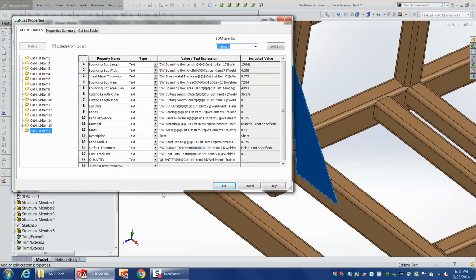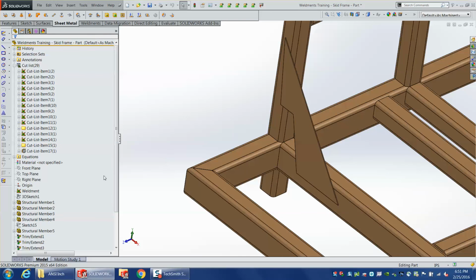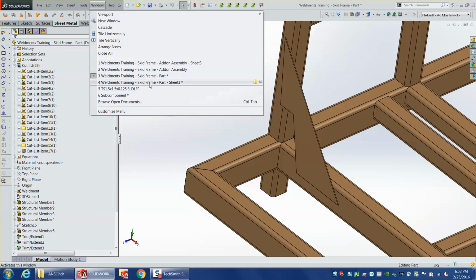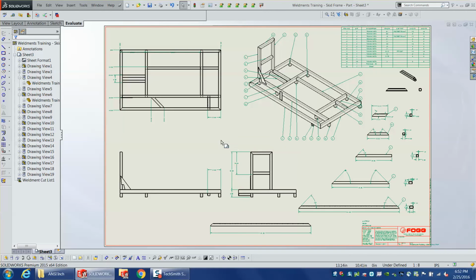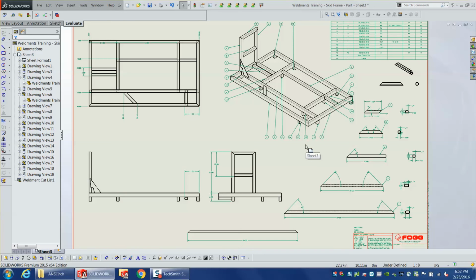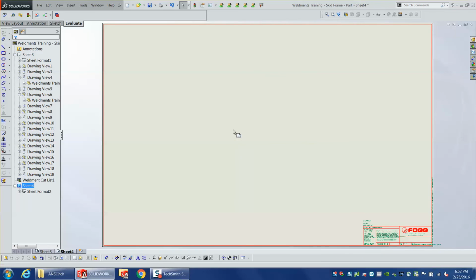It's going to have all the normal sheet metal properties, bounding box, everything like that. So if you needed a separate file, you could. I could save it out from here as a separate part and send it to the sheet metal job. You can also do an external and insert a part into a weldment like that. It's how you're doing the separate views. If you've got to make a separate sheet metal drawing, I do that all the time, where if you've got a frame, you put a drawing on it or something like that.